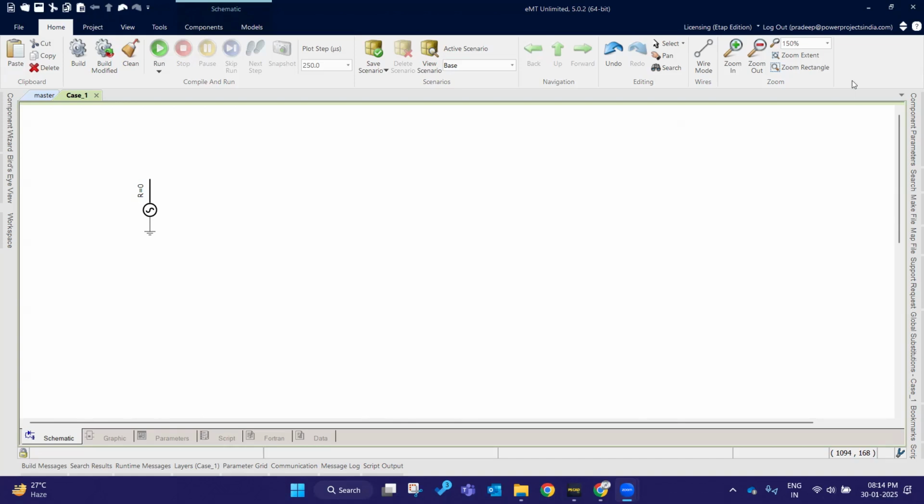In simplification, you just select the transmission line component. You select the phase conductor from the library and the ground wire conductor from the library. If the corresponding element is not available in the library, you develop your own library and your own model and include it. You enter the length, and the RXB parameters are automatically calculated. Upon modeling that, it is enough for running a simulation in ETAP.